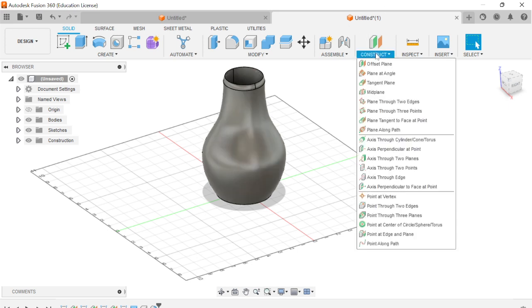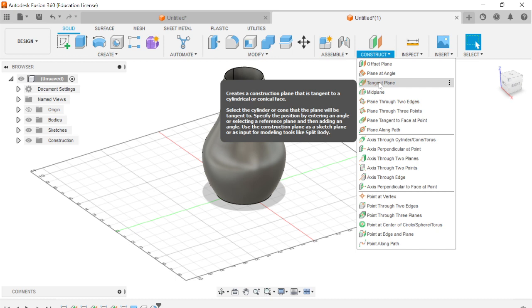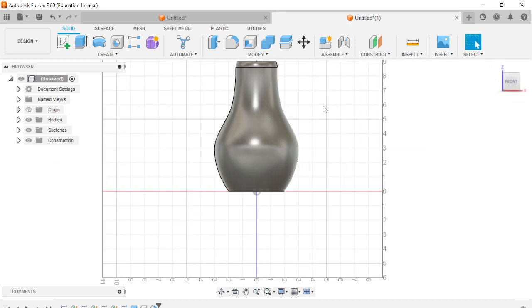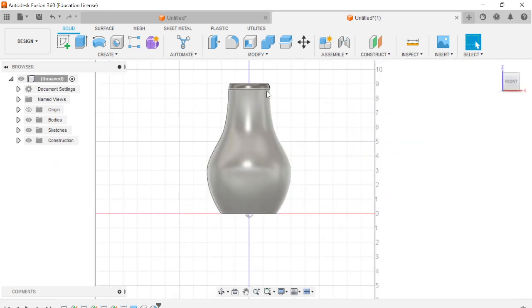So when I first tried to do this, I thought the best way to do it was to add a tangent plane to the outside of this hairdryer. What you'll notice, this is kind of a complex curve, and depending on where your Z coordinate is, you have a different X value corresponding to it, right? So if it was a circle, you would be able to put a tangent constraint because you have that constant radius, but this is a changing value.